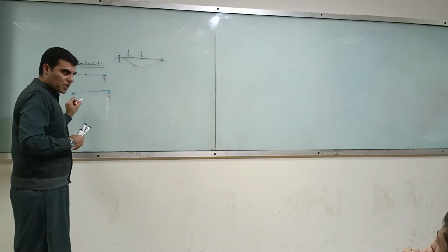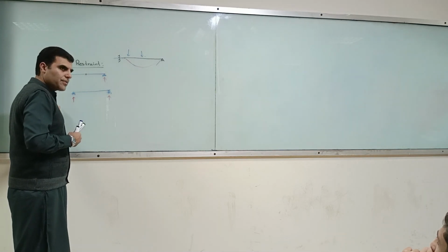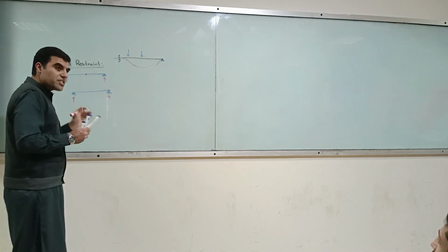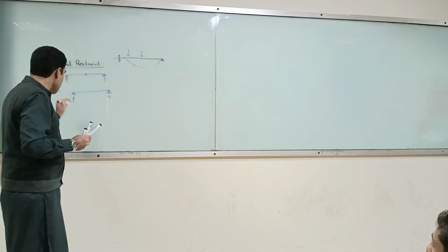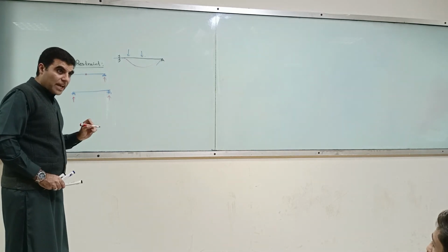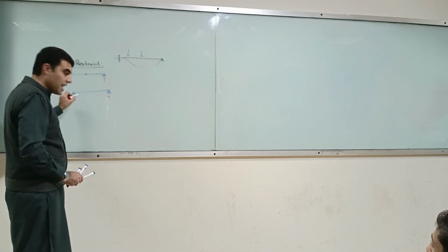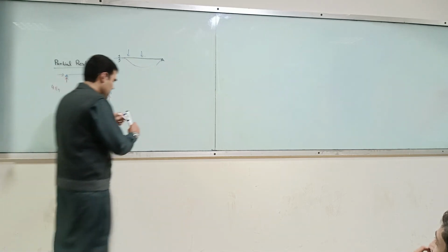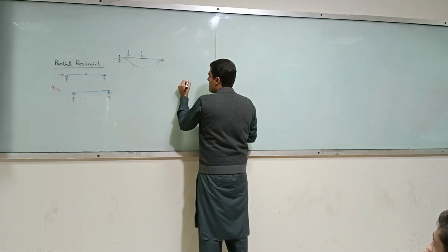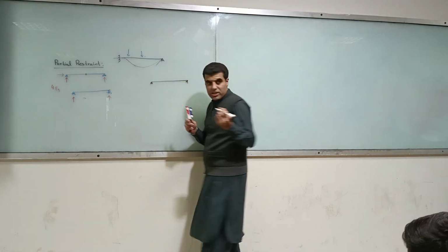If you have a roller support like this, in this case again, you have how many equations? You have got 3 equations, but the available unknowns are 2. So the summation of forces will never be satisfied. So this is an unstable structure, because this will start rolling. Now, if we have a structure having a pin on both sides, with a hinge in the middle,